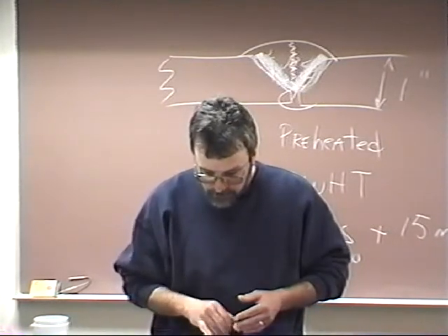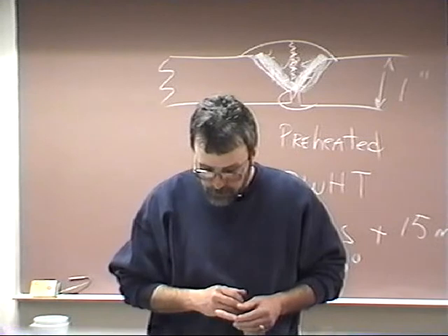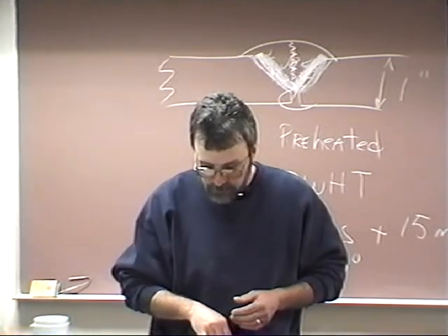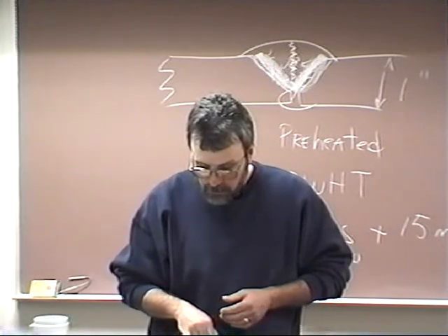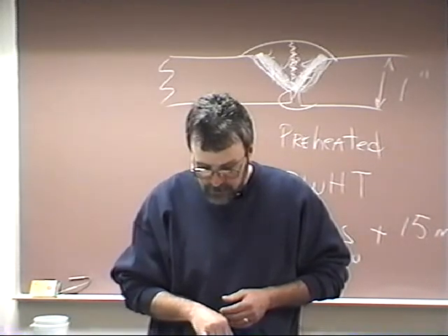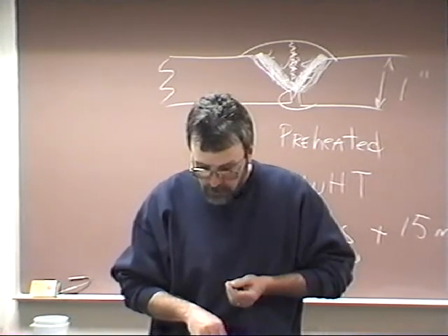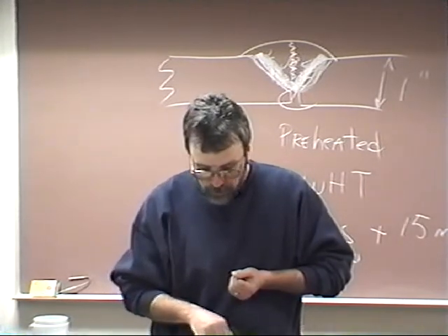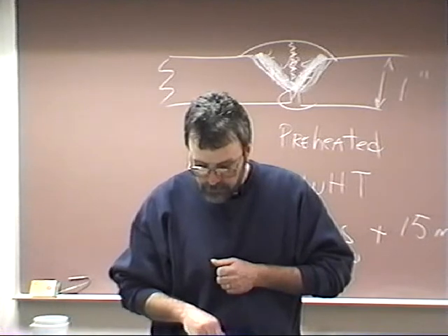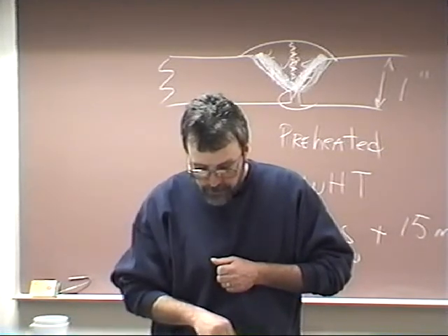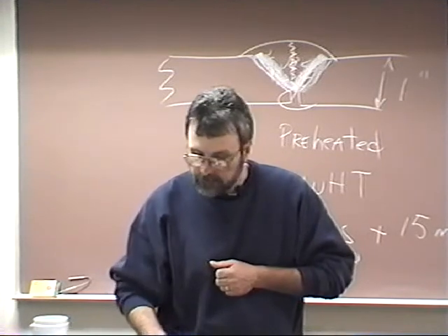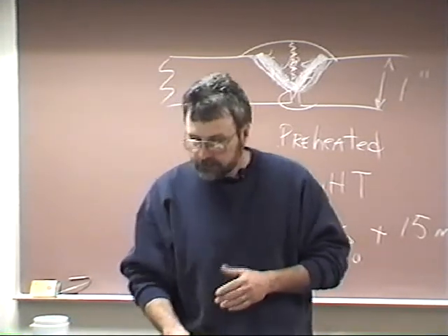Removal of defects. There are two stages of a repair. I'm on page 220 now. It says A, removal of the defects. B, preparation of the defective area for welding. The cavity which has been prepared by gouging or grinding now must be dressed by a grinder or a burring tool that can effectively remove the rough surface of the cavity. The repair cavity must be wide enough so that the electrode can fully access the defective area. So you want to make sure you clean everything out.